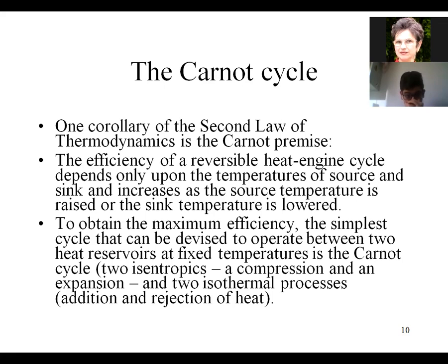So from the Carnot cycle, you know that it is the most efficient cycle. It is an ideal cycle that doesn't exist, and the efficiency is calculated always for a given cycle as 1 minus the ratio between the minimum and maximum temperature in the cycle expressed in Kelvin. The Carnot cycle is mentioned to be formed by two isothermal and two adiabatic reversible processes.